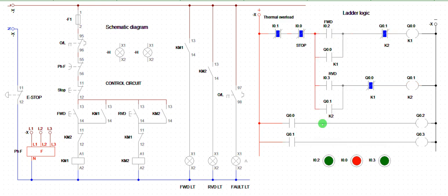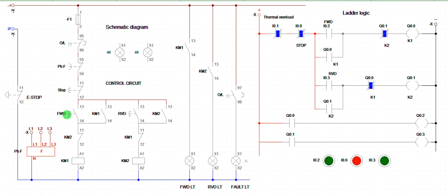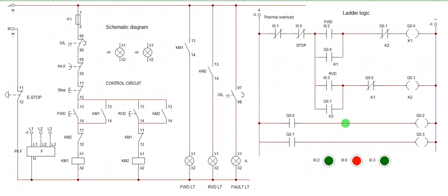the first operation. Similarly, the same way, if I want to simulate this, if I put on this, if you try clicking this one, it cannot get energized because it's open. Until you de-energize this, that is when this one can come in. And once this one is working, this one cannot come in. So that is the essence of electrical interlock.